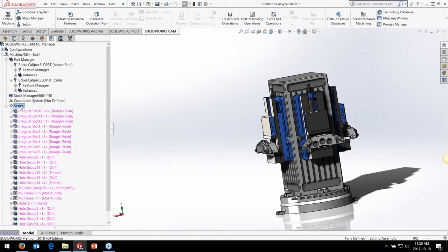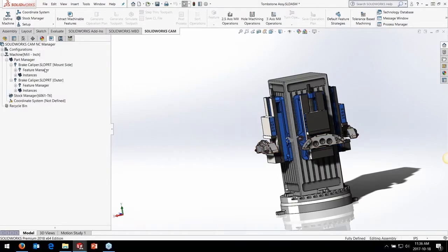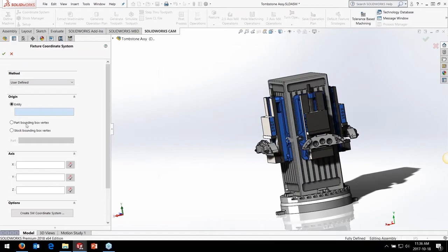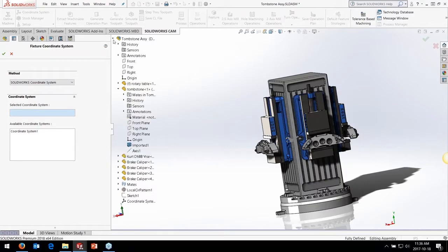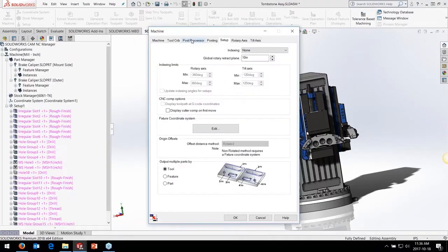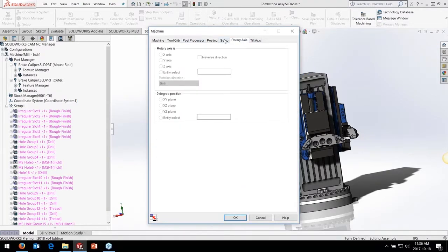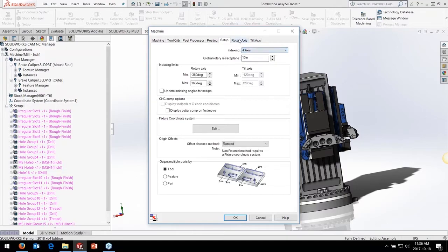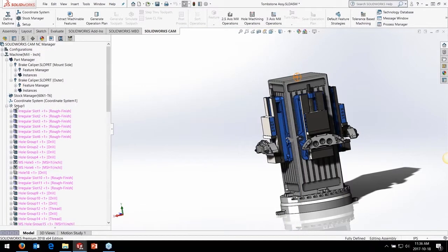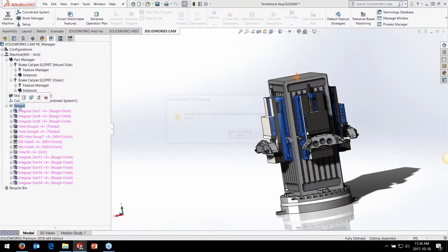I can just import the program into my assembly here, and then I just need to generate the toolpath, make sure it's avoiding things like fixtures and everything else. And I can set my fixtures up. Obviously, there may be some reordering, readjusting of the operations to suit the horizontal and the fourth axis here. But essentially, we can control the indexing and get the rotations out to the code itself. And I will see those rotations.